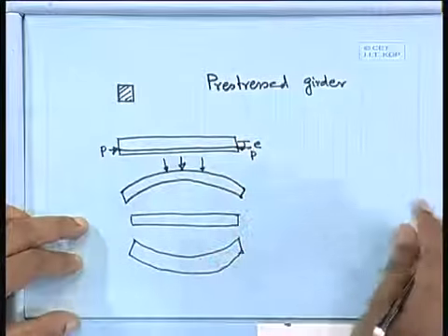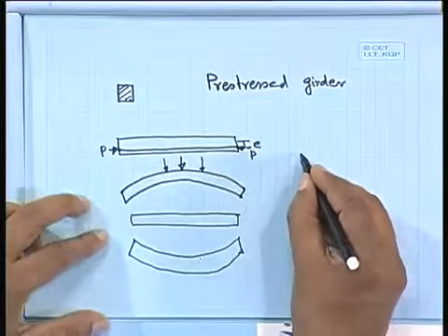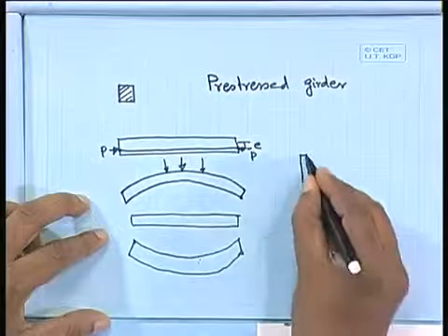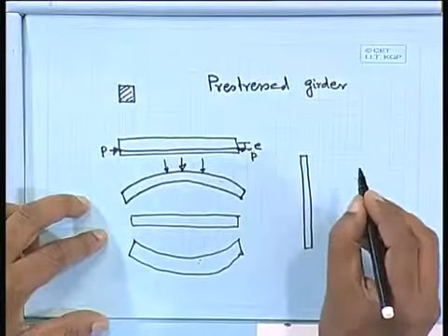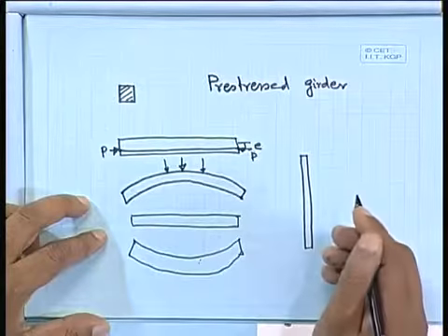But anyway, we are going a little away. Just to conclude on pre-stressing, this is called a pre-stressed girder, and we can go 20 meter, 25 meter, 40 meter, which we shall not be able to do with reinforced concrete. With reinforced concrete beams, we cannot go 5 meter, 6 meter, 7 meter, maybe we can go to 10 meter, but your depth will be enormous. The depth you have to provide, because Mu equal to 0.138 fck b d square. From there you can find out the corresponding depth. If we have more span with the same load, your depth will be more.